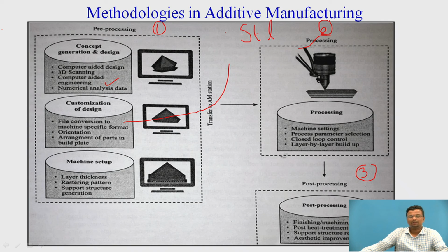because if we insert the 3D model into the manufacturing using the same data exchange format, like for example .dwg, or the .CAT part, there will be huge data loss. Yes, that will be a mistake. We should avoid those mistakes. So .stl is what we can use. We have to decide the layer thickness.